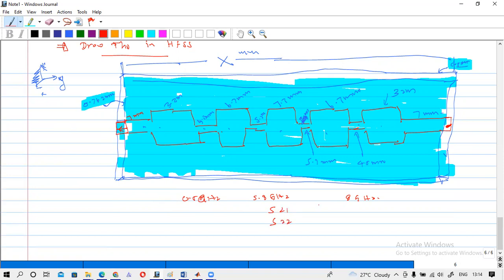You will most probably get this kind of curve. So see what the values are here and here at the 30 dB. These should be matched with our passband edge frequency and stopband frequency. If not, you have to give some reasons for them. So that is your task.